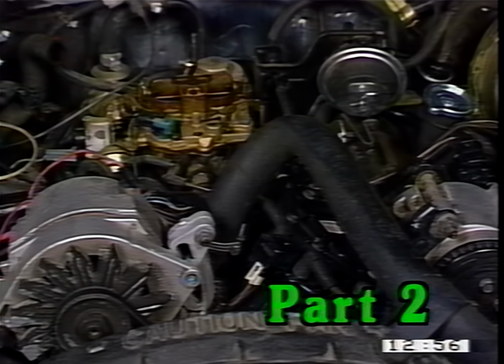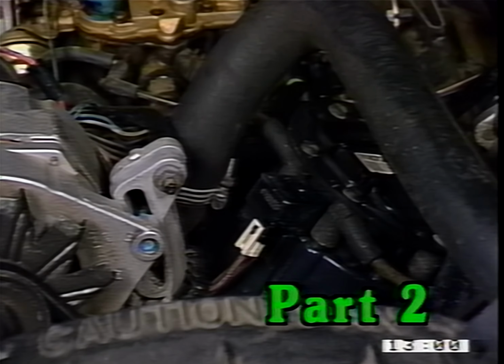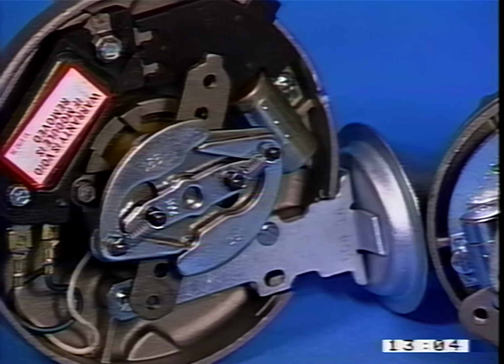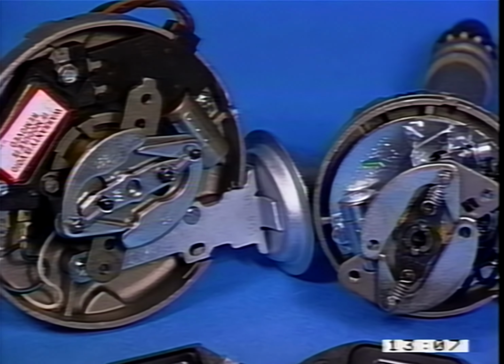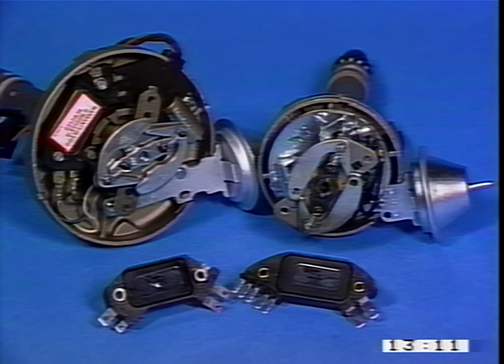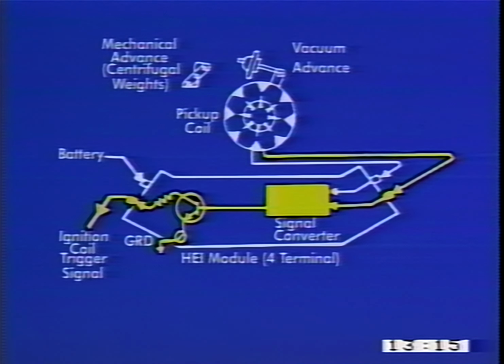The first input we're going to look at is the HEI TAC reference. The C3 distributor is based on and is very similar to the early HEI distributor. Both systems use a magnetic pickup to provide the trigger signal. The trigger signal is an AC signal and is generated by the magnetic pickup. This AC signal has to be converted into a digital on-off signal before it can be used to control the ignition coil switching transistor. The conversion is done by the module, just like early HEI systems.